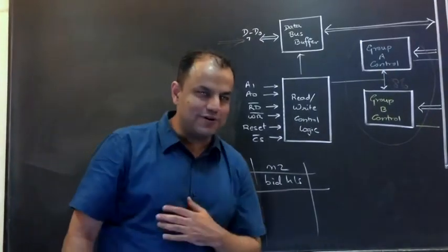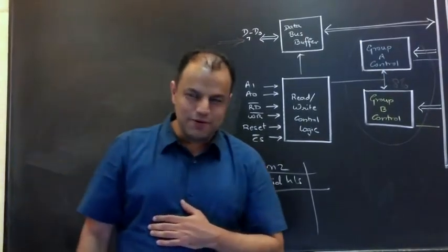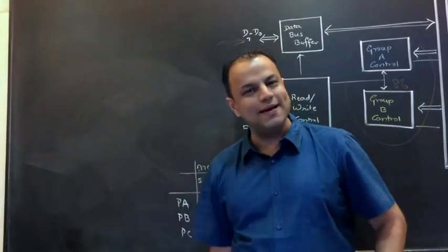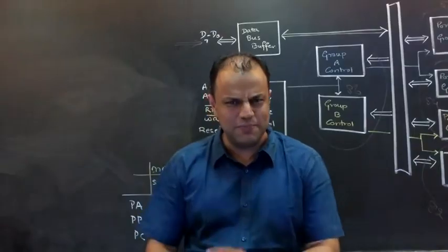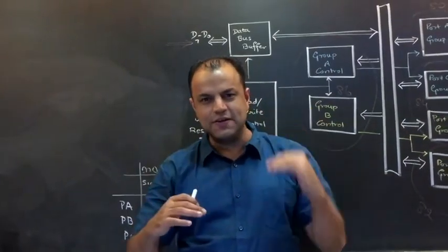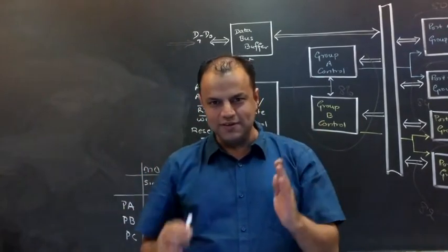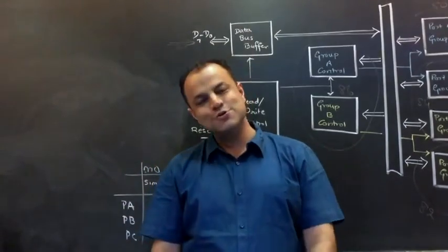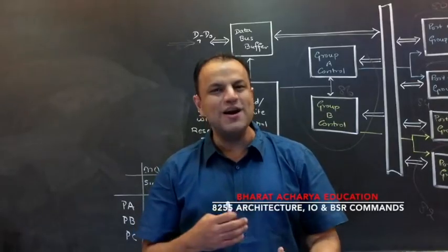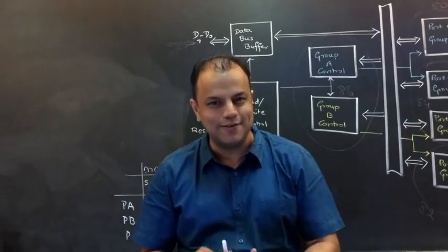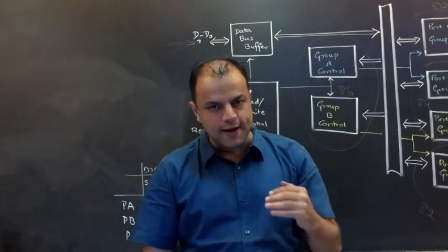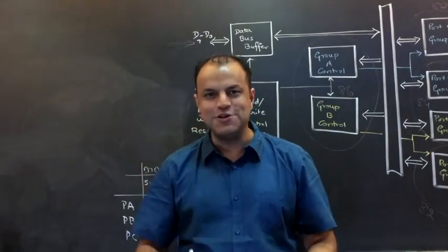Now let's understand what this means. Do you remember, before this, I had shown a simple diagram showing handshaking. Do you remember that brief introductory diagram? In that, there were how many handshake signals? 4. 2 on this side of 8255, 2 on this side. So what do you understand? Any port which wants to do a handshaking kind of data transfer needs 4 additional lines for performing handshaking.